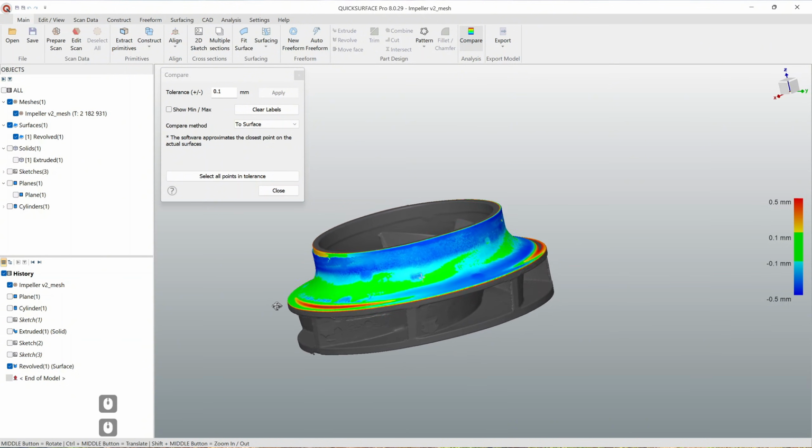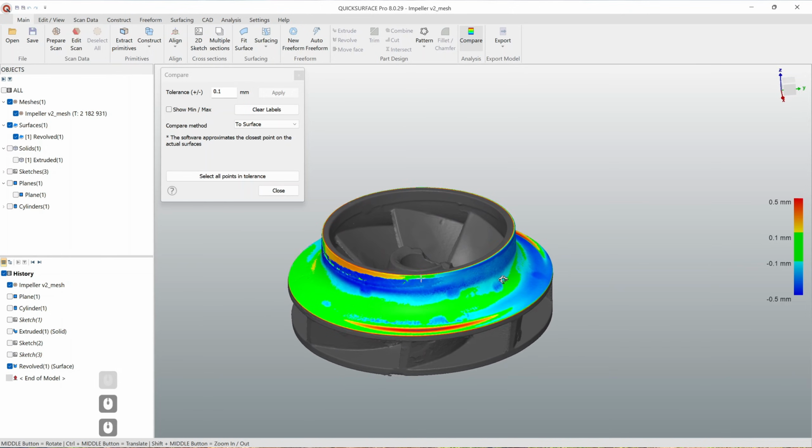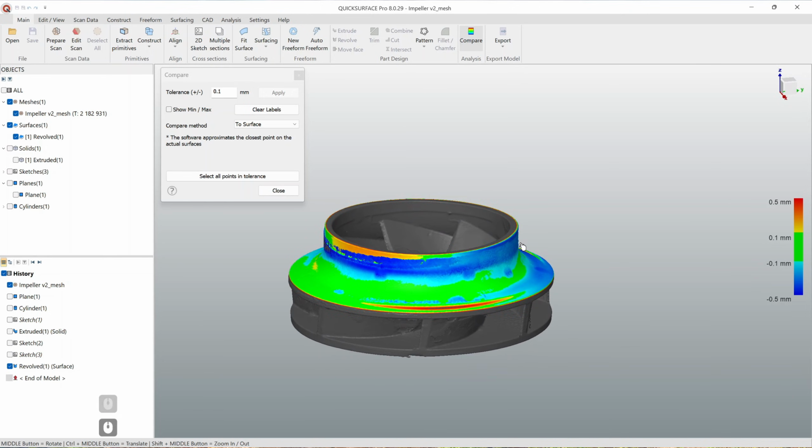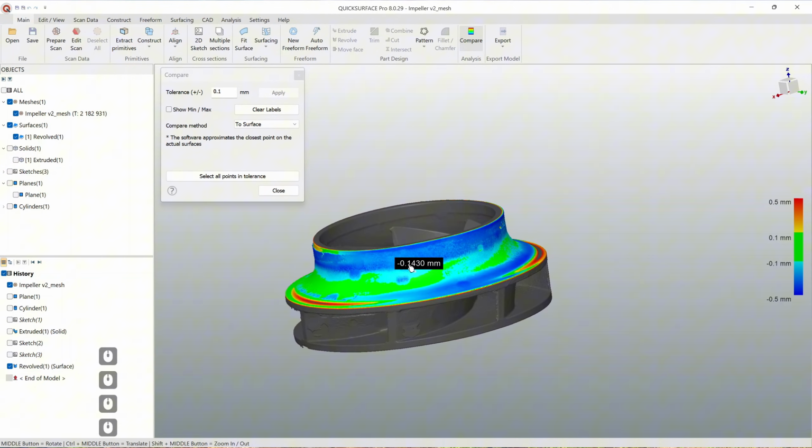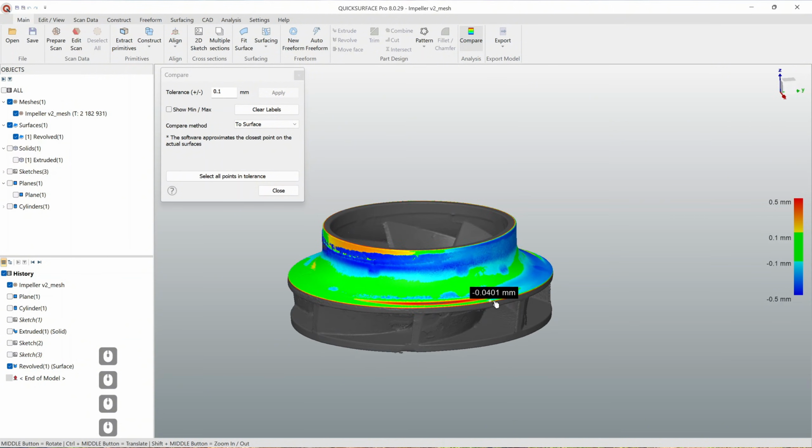Basically, we have to consider something that we can sacrifice in case we want to actually reverse engineer twisted parts. So it's not just about creating some features randomly everywhere. You have to consider how this part was built and how it should work, and just try to minimize locations where you are working on this part.